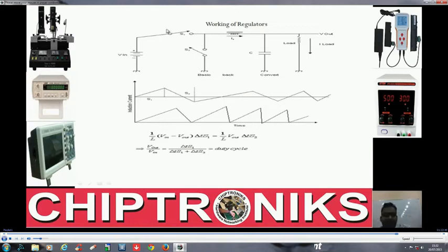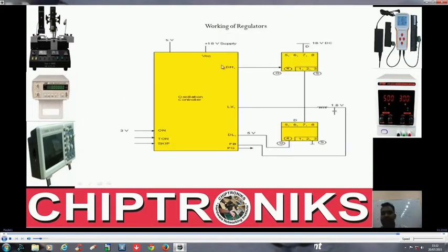In a regulator, you will find two switches. And what are those two switches? The two switches are basically two MOSFETs present outside, and we have one IC, two MOSFETs, one inductor and one capacitor. You see in the next slide, this is the regulator IC, the two switches, the top gate MOSFET, the bottom gate MOSFET, and the inductor and the capacitor.